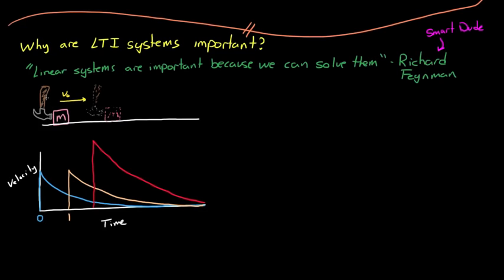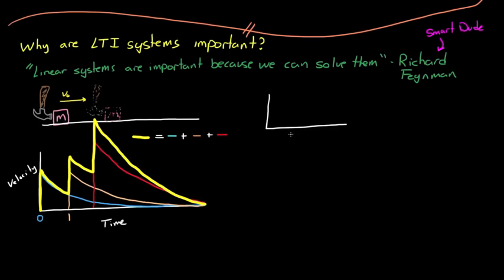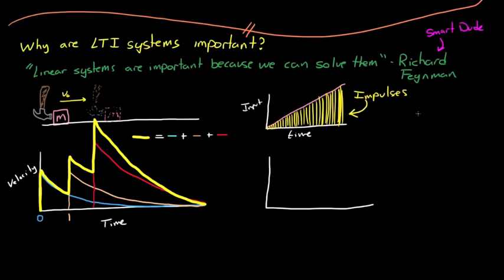And now, finally, because of the principle of superposition, the full response of the system would just be the summation of both signals. In this case, it's the thick yellow line. So you can see that this method works easily with one or two impulses. But what if we have an input into the system that wasn't just made up of one or two discrete impulses, but was a continuous ramp? And further, if we broke that ramp into a series of sequential impulses, then with an LTI system, we can say that the output is the summation of the responses to each of those individual impulses.